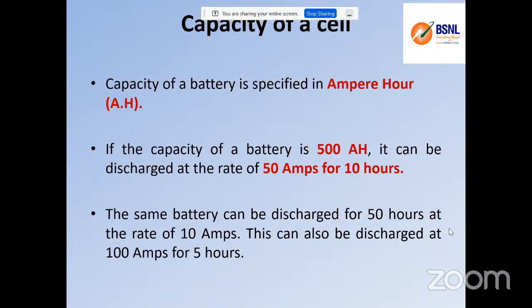So we will see in the next slide. That means there will be an over current limiting factor. So normally they will design it at the time of manufacturing itself. That's the reason if any short circuit happens, an immediate fire will catch, because the battery cannot have any particular control. So the battery has to be properly maintained and properly handled. There should not be any short circuit between these two terminals. Otherwise it will be making maximum current.